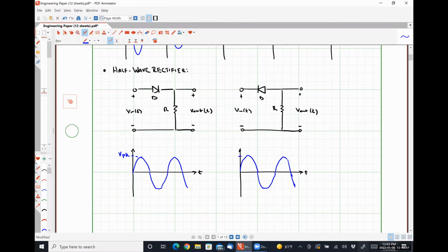And that's something that's critically important, so I want to talk about it for just a moment here. When we're specifying a transformer, typically speaking, we're dealing with RMS voltages on the primary side and RMS voltages on the secondary side, right? So for instance, if we have a 10-to-1 transformer connected to a 120 volt RMS 60 hertz source, then the output on the secondary windings would be 12 volts RMS at that same frequency of 60 hertz, right? All of the math that we're going to wind up doing for these half wave and full wave rectifier circuits does not use RMS values of the voltage.